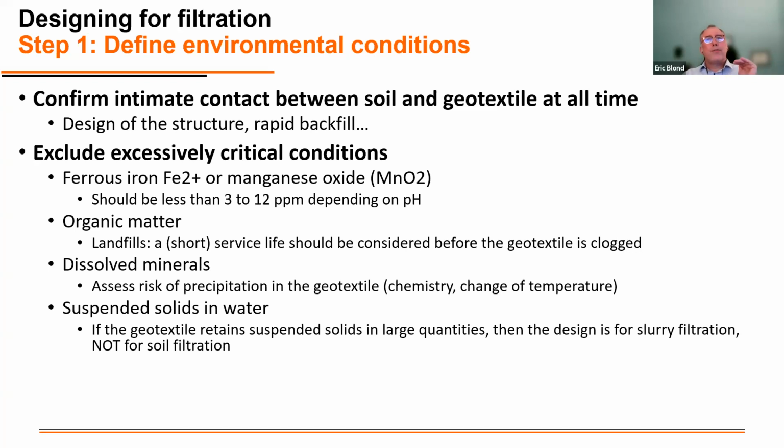So in presence of this type of product, you have to expect some maintenance, some replacement of the geotextile filters. Organic matter, same thing. It's typically not going to go well. If the service life is short enough, that can work very well. After some time, we don't care if the system is clogged, fine. But if it's a long-term project with organic matter, it's not going to work.